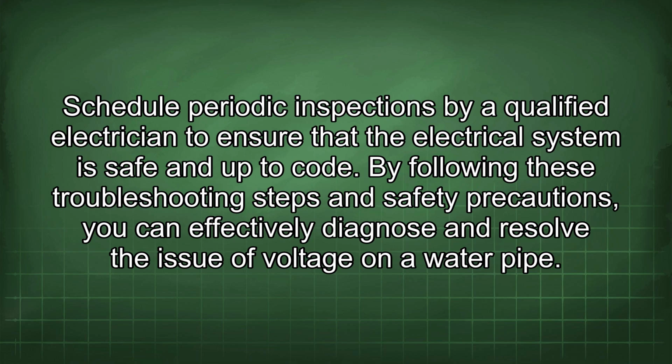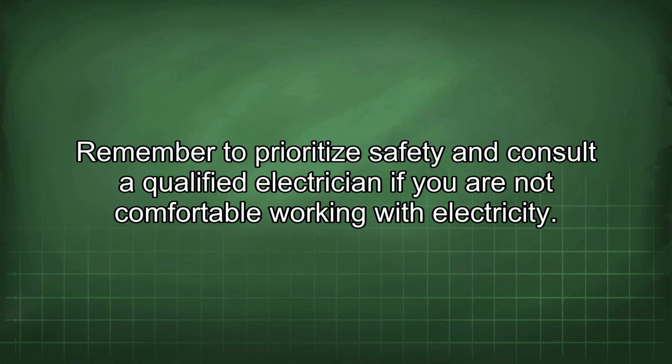By following these troubleshooting steps and safety precautions, you can effectively diagnose and resolve the issue of voltage on a water pipe. Remember to prioritize safety and consult a qualified electrician if you are not comfortable working with electricity.